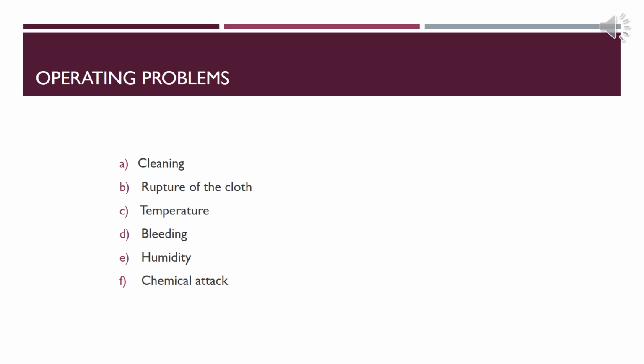Temperature. Fabric filters will not perform properly if a gross temperature overload occurs. If the gas temperature is expected to fluctuate, a fiber material that will sustain the upper temperature fluctuation must be selected. Also, whenever the effluent contains a reactive gas like sulfur dioxide, which can form an acid, whenever the temperature in the baghouse falls below the dew point, it can create problems. Sometimes, it may even be necessary to provide an auxiliary heater to make sure that the temperature in the baghouse does not fall below the acid gas dew point.